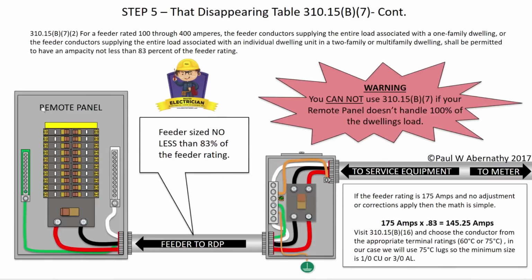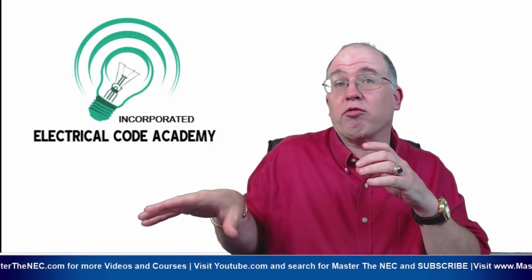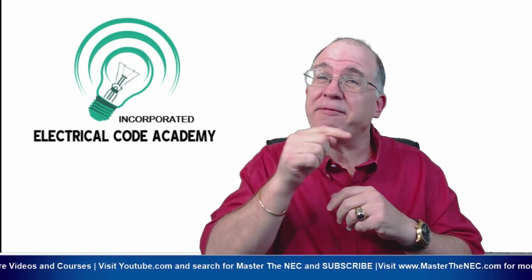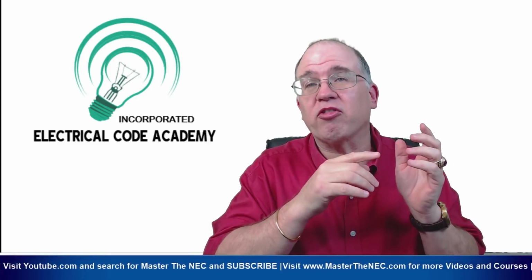Oh, I should also tell you, this has to handle 100. These feeders have to handle 100% of the load. Okay? If I go from here to a panel, that's fine because the load's actually starting here. If I had a panel over here where this single is right now, and it had a couple breakers in here, and let's say that first service disconnect there was actually outside and it had a couple breakers underneath it. And let's say the air conditioning unit's right here. I just want to drop out of it and feed that air conditioning unit. Well, that feeder is not seeing 100% of the load to that remote distribution panel.